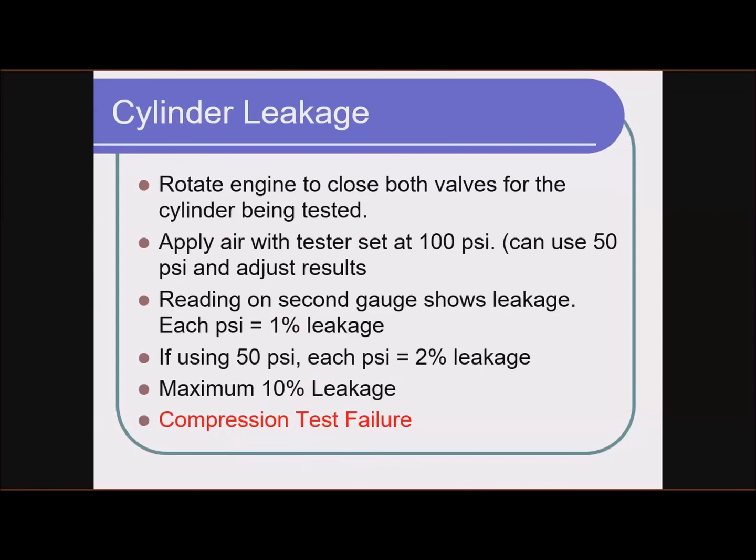So what we're going to attempt to do with a cylinder leakage test is find out which direction the pressure is going. Is it going out the intake? Is it going out the exhaust? Or is it going into the crankcase?